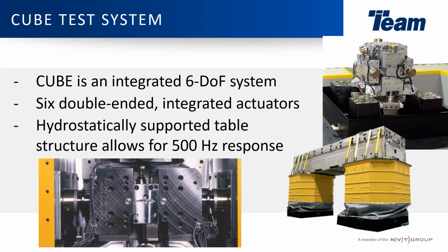And the pad bearing is essentially a spherical coupling that provides friction-free motion in the translational axes, as well as in all rotations for which it's connected to. By doing this, the cube box, so the yellow component on the bottom right picture, is not mechanically connected to any of the actuators. The added benefit here is you do not have excess moving weight in different axes when you're trying to excite that payload.